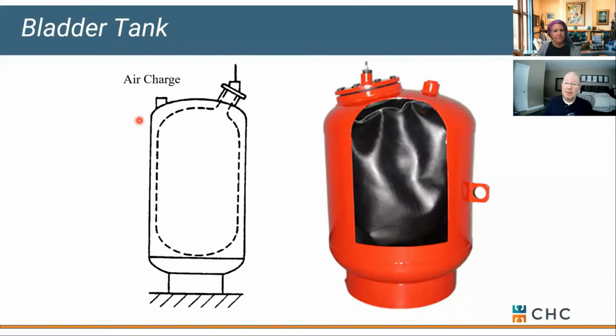An advantage of a bladder is the fact that it's replaceable. Now, for anybody on this call who's had to replace a bag or a bladder, I feel you, it is not an easy process. You've got a lot of resistance trying to get a big bag through a pretty tight little collar here. So sometimes you got to lube it up. Sometimes you got to get some mechanical force like a forklift or, in my case, maybe an excavator at home or a come-along. You need some help to get this bag out of this tank. It's not an easy setup, but it can be done.